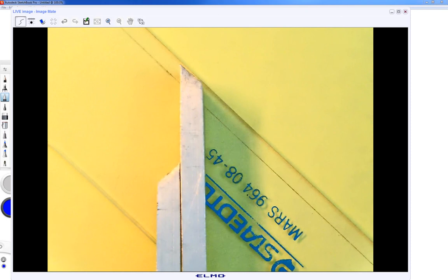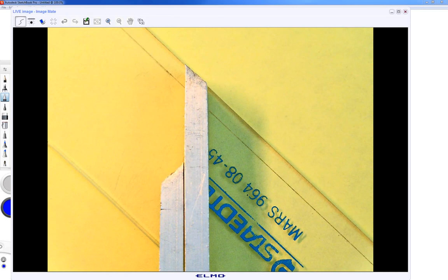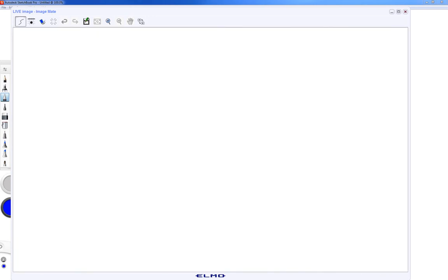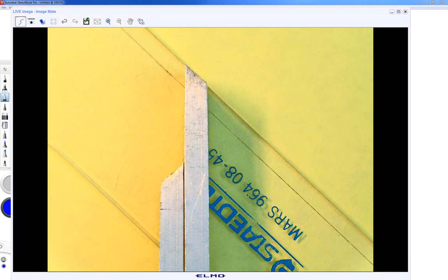I'll bring this down a little bit. See if I can get that to focus. Okay, make sure the bottom's lined up, and there it is. That's really, really close to 45 degrees, and I'd say that's as exact to 45 degrees as you can get. So this was a ductile aluminum material. We pulled it in tension, and it failed right at that 45-degree angle, just as that theory has predicted.